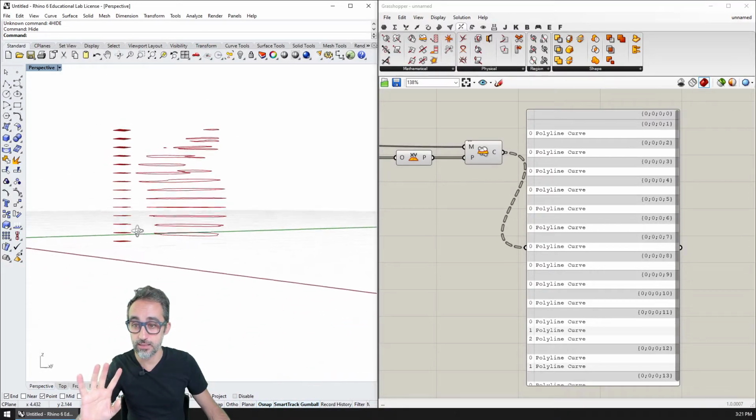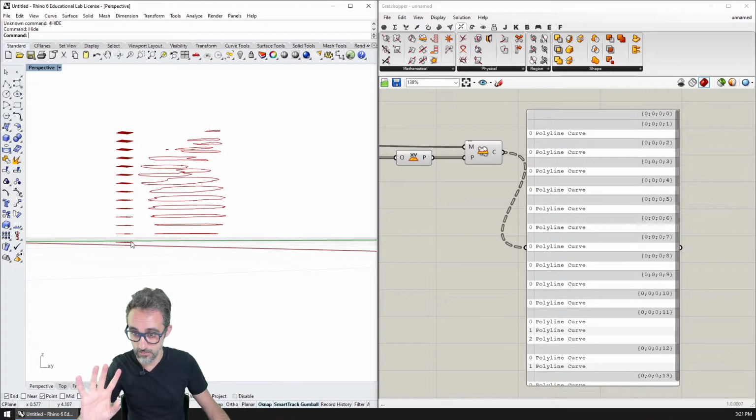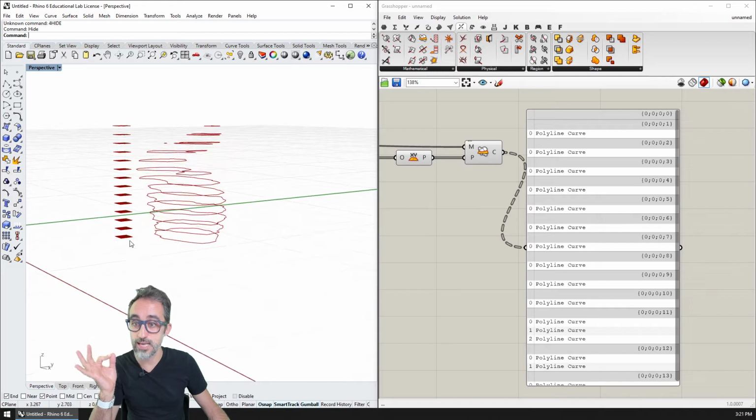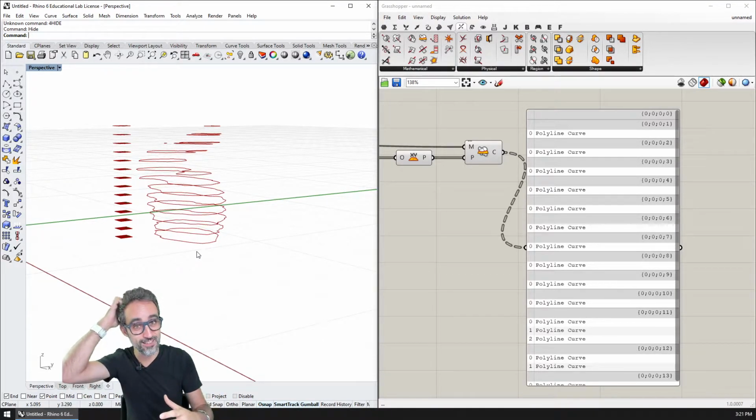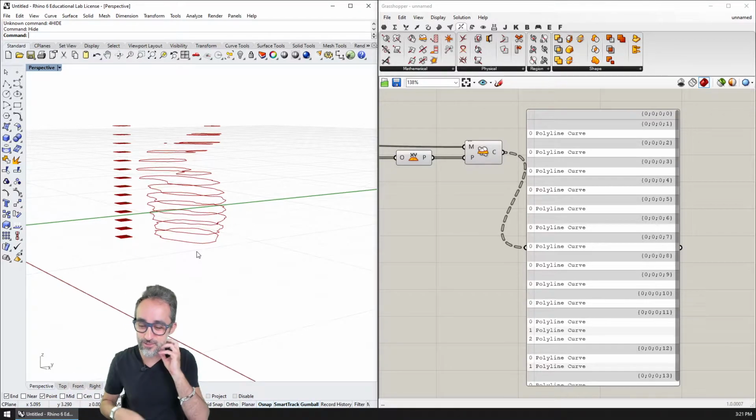And we can see that the very first one, because it's coming from this bounding box, is giving me no intersections, which would be a terrible thing for 3D printing, because in 3D printing we actually really need a base to stick to the base of the printer. So that's something that we should definitely improve at some point. But you can see how we have an empty branch here.